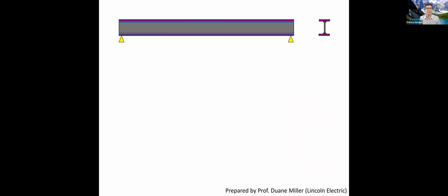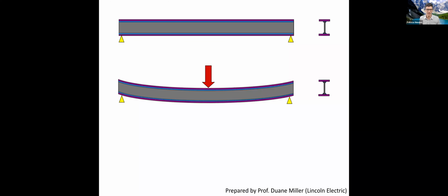In the case in which we have bending, for example, in this case, this is an I-beam that is manufactured with fillet welds. This is a case of huge I-beams. For example, Supreme Steel makes these types of beams for bridges. In countries such as Chile that are fairly remote, in this southern tip of the Americas, and without a strong steel industry, they manufacture pretty much every I-beam, because it doesn't make sense for them to have a large stock or to wait too long to import. So I-beams are often manufactured either because they're huge or because there is no economy of scale.